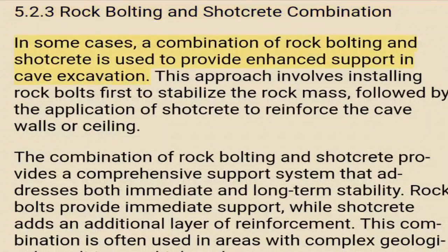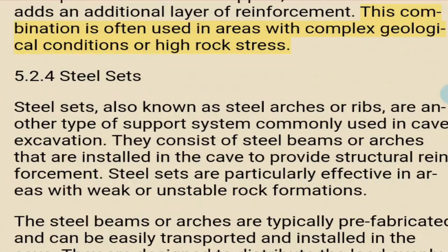In some cases, a combination of rock bolting and shotcrete is used to provide enhanced support in cave excavation. This approach involves installing rock bolts first to stabilize the rock mass, followed by the application of shotcrete to reinforce the cave walls or ceiling. The combination of rock bolting and shotcrete provides a comprehensive support system that addresses both immediate and long-term stability. Rock bolts provide immediate support, while shotcrete adds an additional layer of reinforcement. This combination is often used in areas with complex geological conditions or high rock stress.